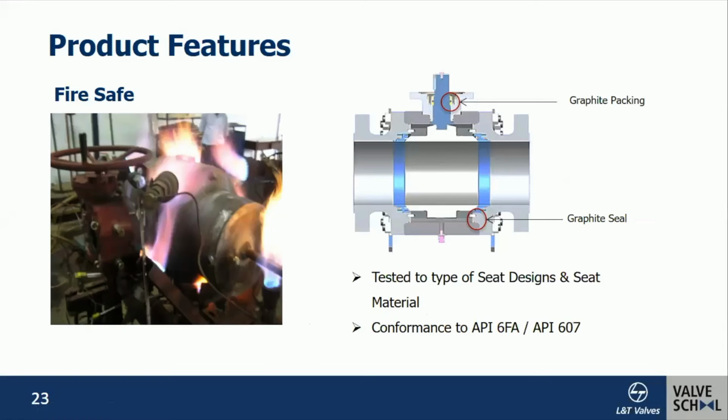The valves are fire safe tested with the different types of seat designs and the different body constructions. We have tested all the two-piece designs, a three-piece design, and the top entry ball valves. Primarily the conformance is to the American Petroleum Institute standards like API 6FA and API 607.